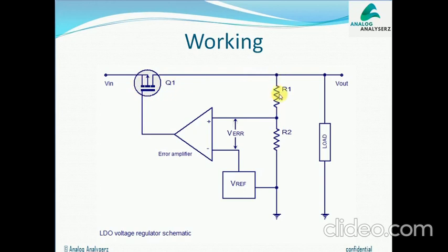That was the normal working, wherein Vout is appropriate and PMOS is giving the appropriate voltage. Now take a scenario wherein the output voltage has gone up from 1.2 volt to 1.6 volt, so it has moved out of its range. What will happen? This resistor network will give some drop. Earlier for 1.8 it was 0.7, now for 1.6 take it as 0.9.